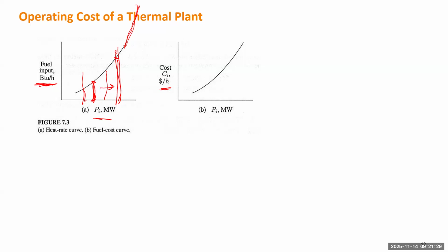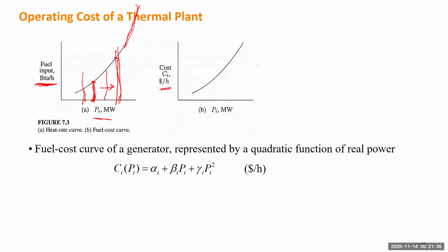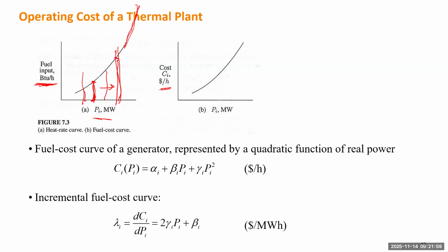So we are going to do optimization based on this curve. This only gives you the price for a single power plant. We are going to collect such curves from all power plants, and we figure out which power plant generates how much to give the minimal cost. As I said, we don't have to explore the entire curve. We only focus on maybe one region of the curve, starting from the minimal output to the maximum output,